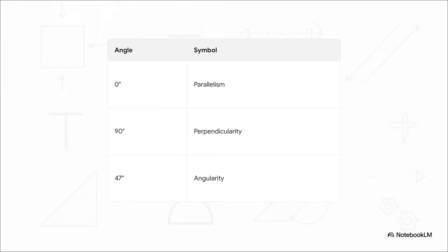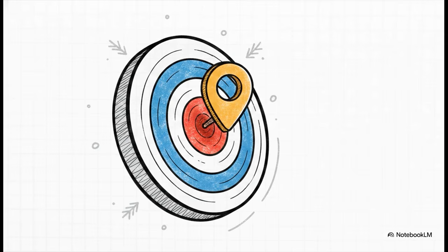If you nail those, congratulations. You've just taken a massive step toward GD&T mastery by truly understanding how orientation controls actually function on a blueprint. But as always, our journey doesn't quite end here. Think about the logical flow of manufacturing a part. First, a part needs basic form. It needs to be round or straight. Next, as we learned today, it needs proper orientation. It needs to be perfectly tilted, parallel, or perpendicular to its datum anchor.